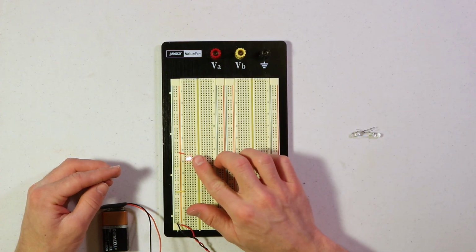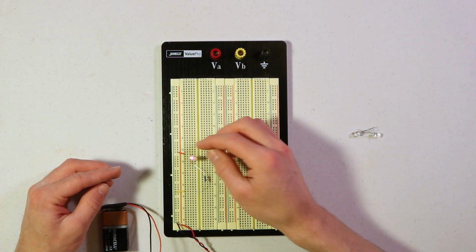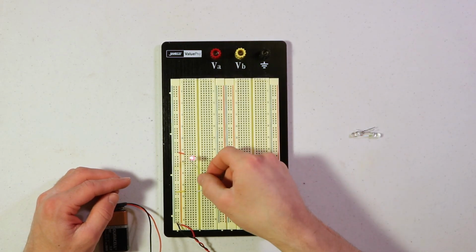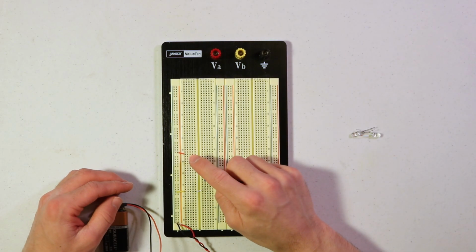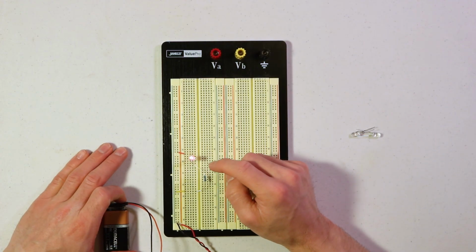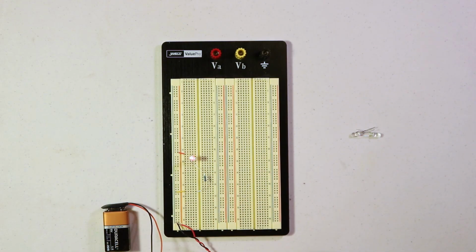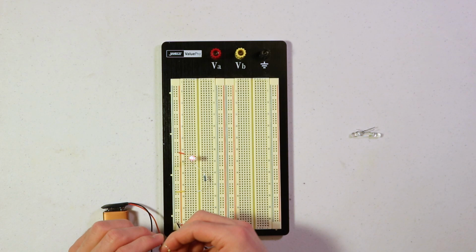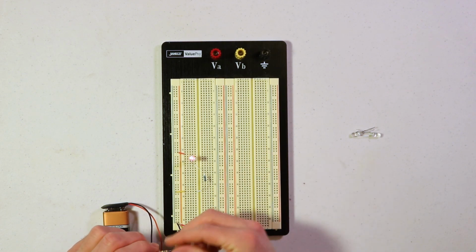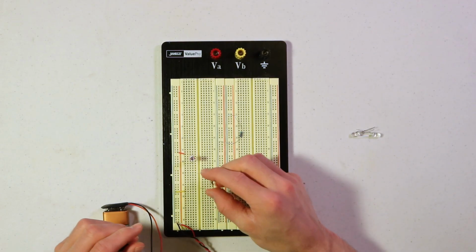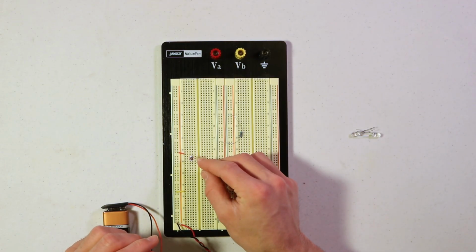Alright, so right now the LED is on, and you can try this, and right now it's kind of dim, but you'll find that the current that flows through an LED is what's going to determine the brightness. So this is a large resistance, 5.1 kilo ohms, and now if I swap that out for this 470 ohm resistor that we were using before, the resistance is going to be less, so the current should be more. And we can check this now.